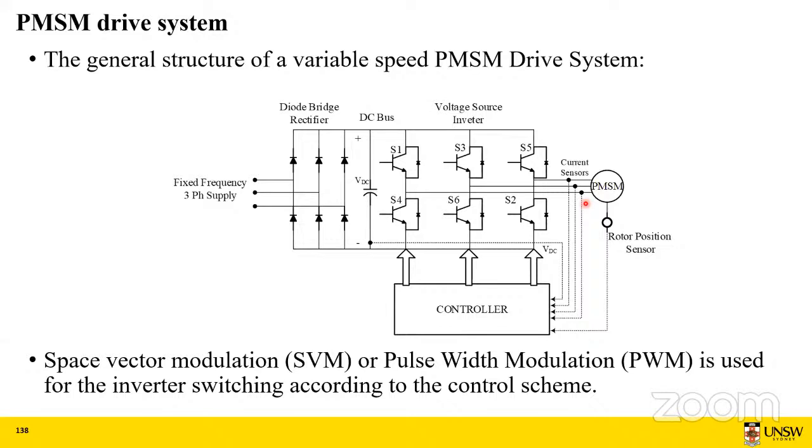However, we need to remember that our rotating magnetic field is rotating at the electrical synchronous speed, which is quite fast. Whereas the rotor is a mechanical thing, right? It could have very large inertia. So if we imagine that rotating north pole of your stator trying to pull the south pole of your rotor, before it can pull to a certain position, the north pole of your stator will change to south because the rotation is so quick.